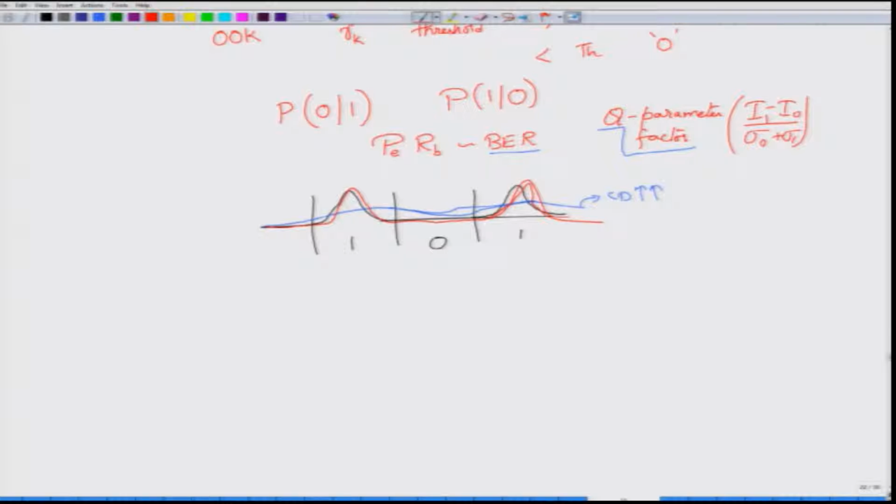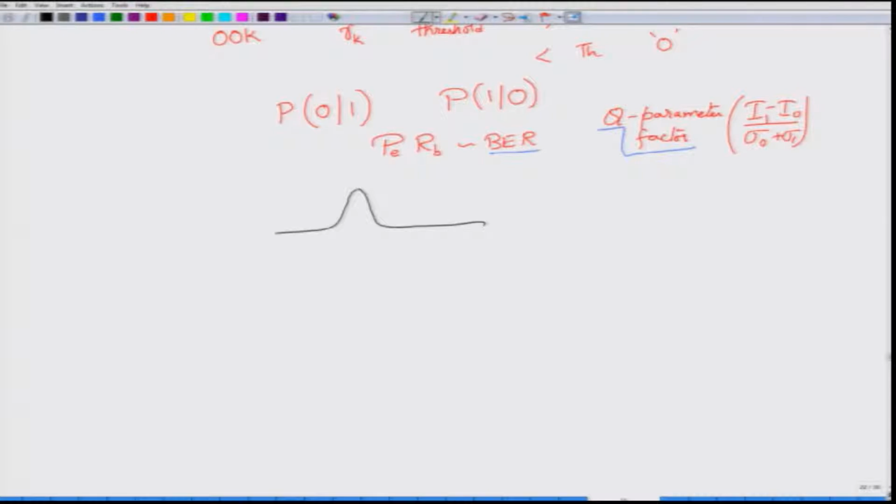This will be a very important factor because earlier you were sampling at the maximum point. Now, because of this error or the jitter in the arrival, your sampled voltage will actually be less. For example, let us say this is the point where we were sampling originally. So, this is my original sampling point. Now, because of the delay or the jitter which is random, the signal did not arrive at this point, but rather the signal peak occurs after some time. But my sampling time is still the same, right, and what would be the sampling value? That would be this blue color one.